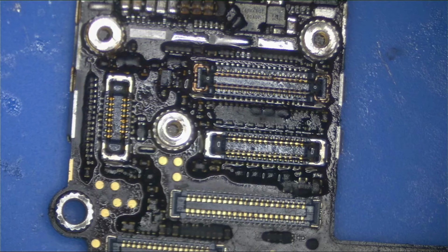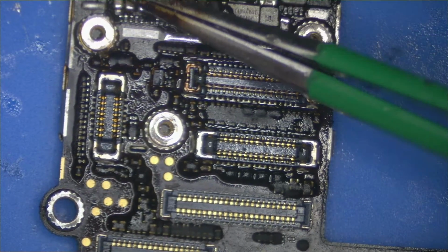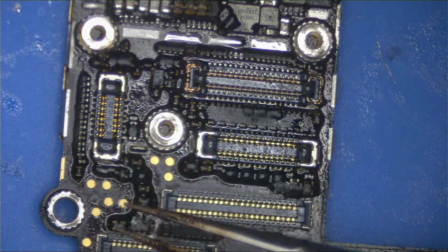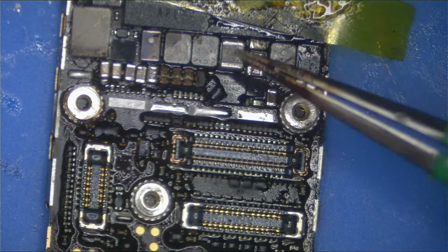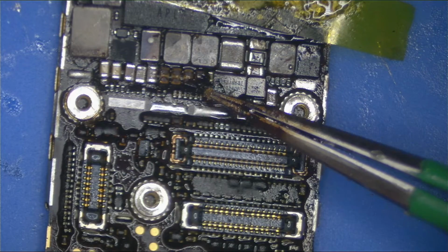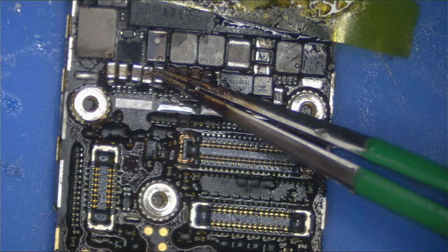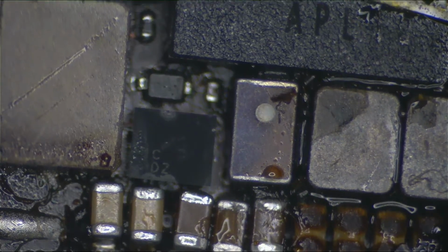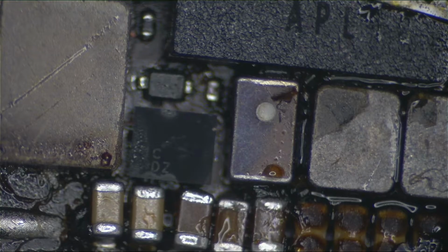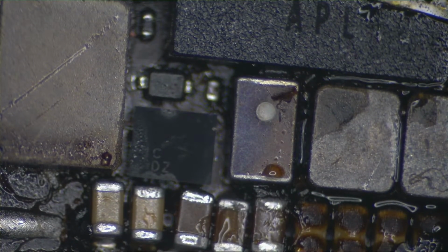Now we all say it's actually the coil on the iPhone 6, which is kind of crazy. So our theory is that when one of the caps shorts to ground, all that current melts one of the inner windings on the coil and causes an internal short, and that's what causes dim or flickering backlight on the iPhone 6.